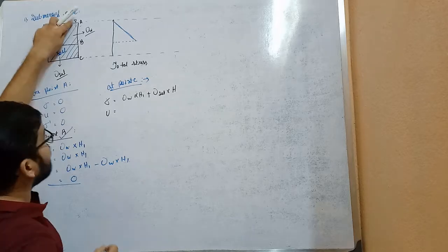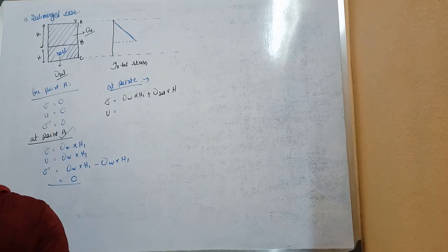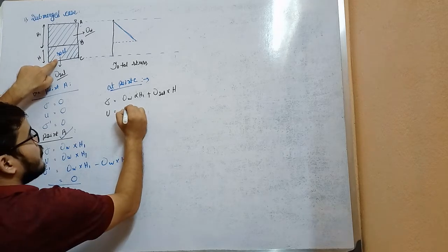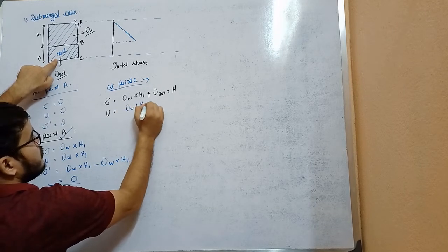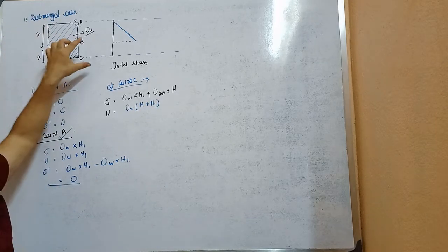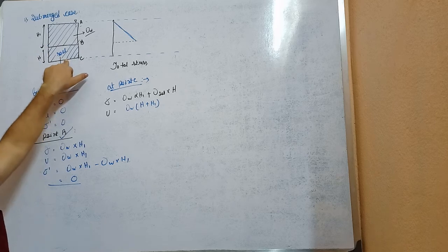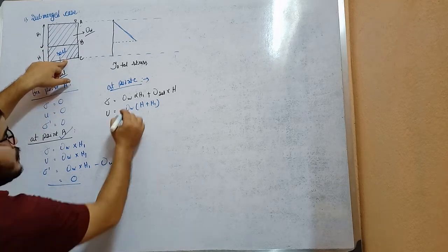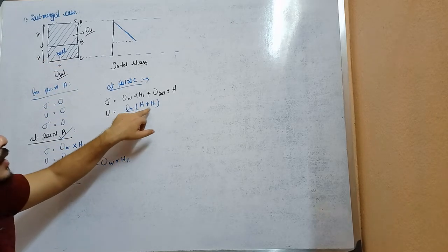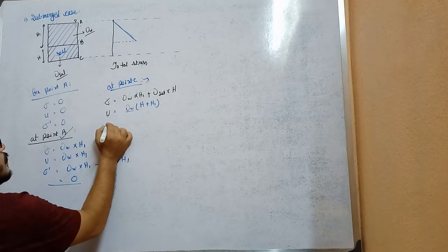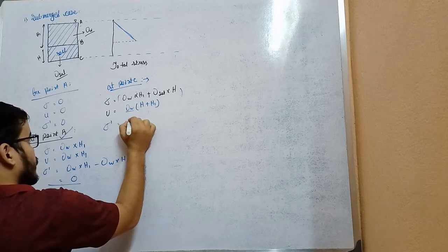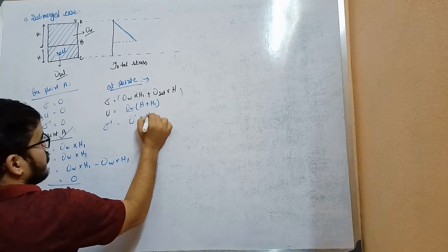The water table is present here. So the total height of the water table from this point is H plus H1, the height of the water table from the concerned point. Then multiply it with gamma W, then you will get the pore water pressure. So gamma W into H plus H1. So effective stress will be this minus this. That will be gamma submerged into H.